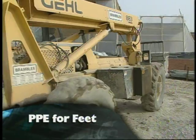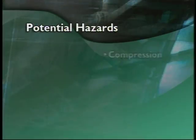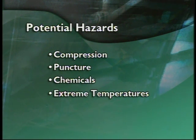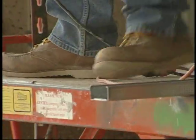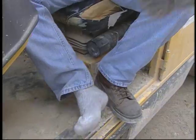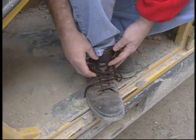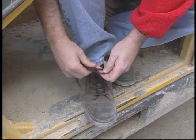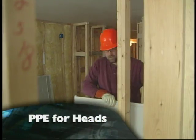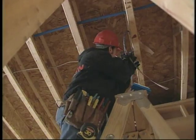At construction sites, a lot of potential hazards exist for foot injuries. These include compression, puncture, chemicals, and extreme temperatures. To protect your feet, wear safety shoes or boots with steel toes and puncture-proof soles. To help prevent foot discomfort, safety shoes and boots should be cushioned, flexible, water-resistant, and breathable. Head injuries are also common at job sites. Most often they occur as a result of bumps, falling and flying objects, and electrical shock.